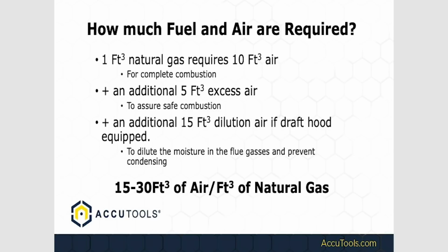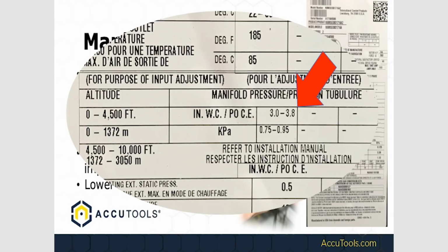In fact, anybody here do work on propane? Bunch of you guys, right? You guys don't really panic over changing orifices, do you? Right? You have to go out and convert natural gas appliances to propane all the time. For guys that are in classic gas markets that never convert appliances, maybe you've seen for years, it's 3.5 inches. Got to set it at 3.5 inches. What does that say right there? Manifold pressure.